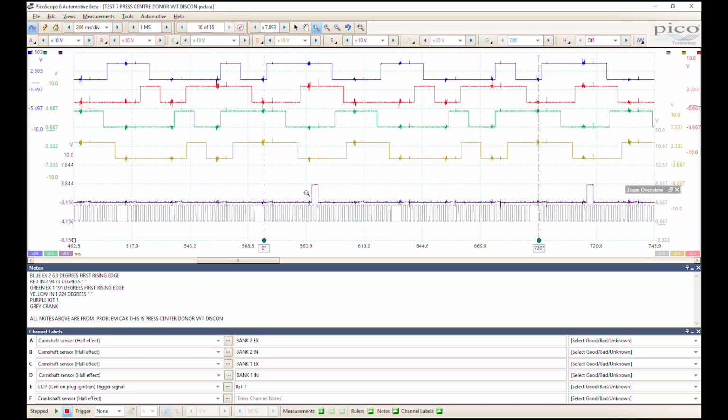Okay, remember this can shift slightly because it's an ignition timing event. This will not shift, but this can because of advance and retard. So we'll forgive that if it's not quite bang on. Nevertheless, we know that it's this point to measure from. Certainly not this one, because IGT after this point is all the way over here for cylinder 1.